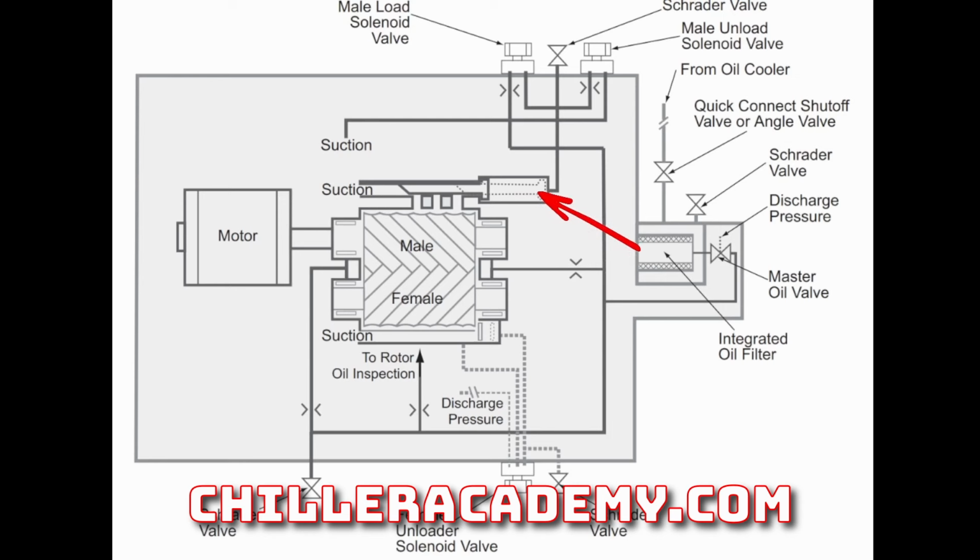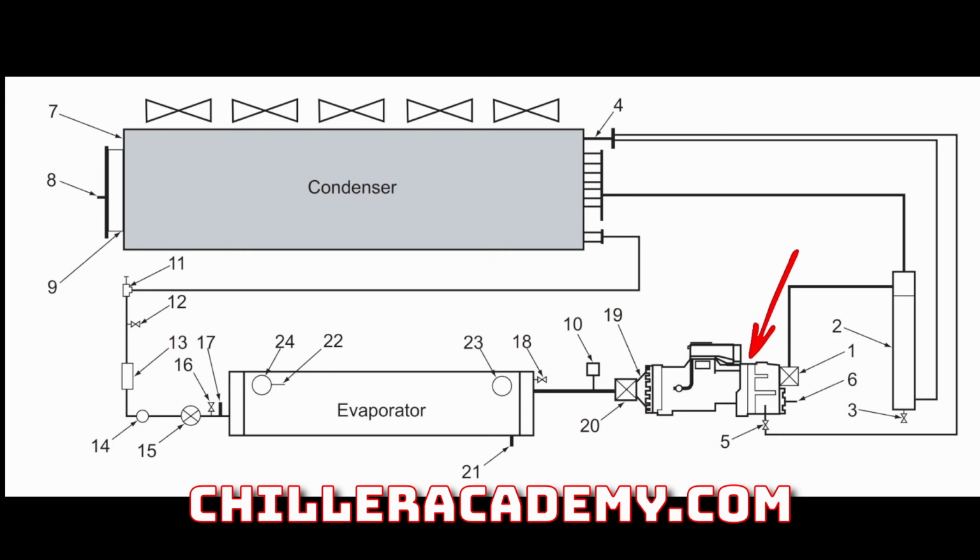So in a single compressor setup, short of it being a very high load that is beyond the chiller's maximum capacity, it's reasonable to say that once it gets somewhere in the middle section here, it will stall out. It's going to stop pushing the load valve, or the slide valve, over, and we're just going to maintain the load where we're at right there. We don't need to go any further. And so that's where this really separates itself from the other compressors.